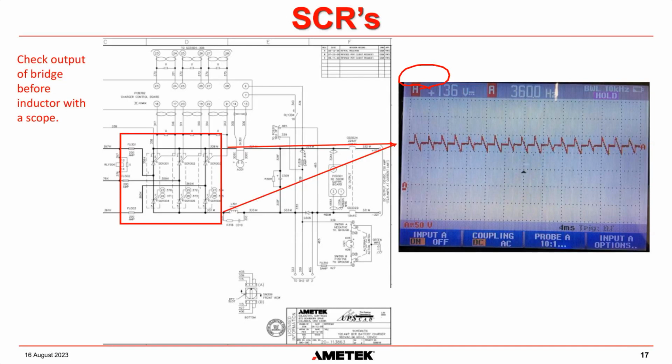And the other important thing is, on that screen for the oscilloscope that you can see there, all of the pulses are uniform. Okay, you can see that they repeat one after another after another. Everything looks symmetrical. Okay, so everything is good on this picture here. I'm not going to explain exactly what's going on, but that's roughly what the output of a three-phase full wave bridge rectifier output should look like when you look at it with an oscilloscope.